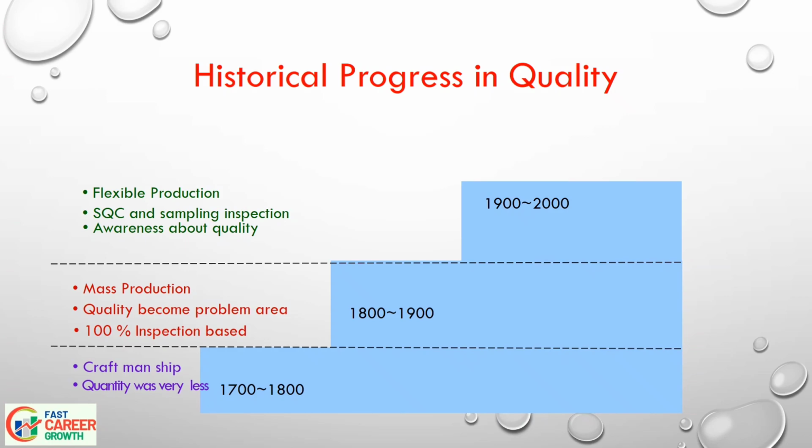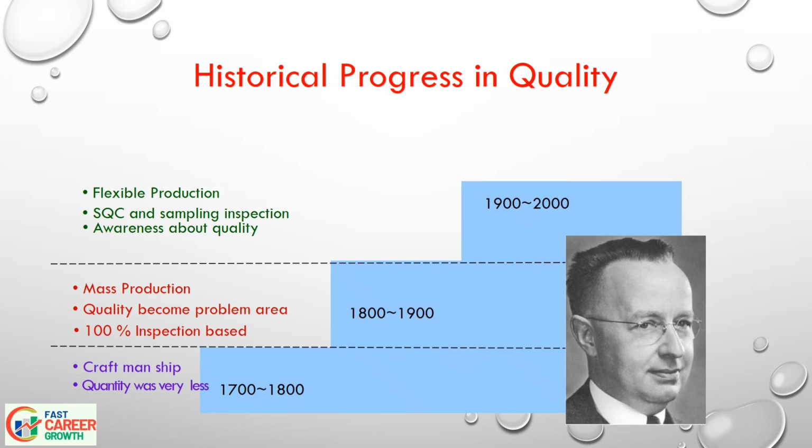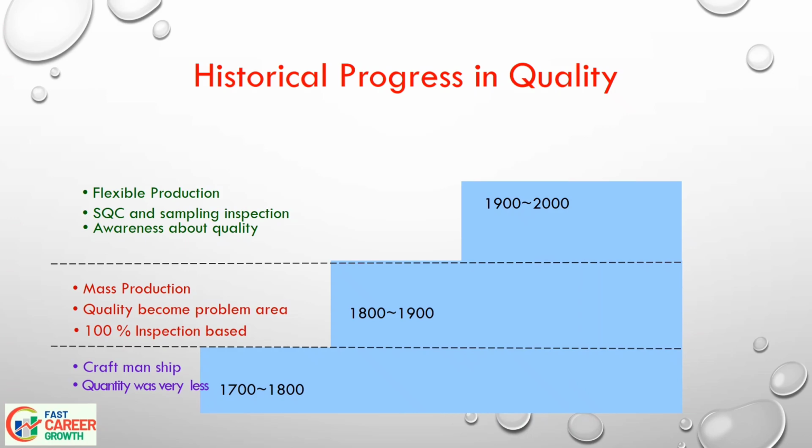In 1924 Walter Shewhart of Bell Telephone Laboratories introduced the concept of statistical quality control, controlling the quality of mass-produced goods. Shewhart believed that variation always exists in manufactured products, and that the variation can be studied, monitored, and controlled using statistics. In particular, Shewhart developed a statistical tool called the control chart. Such a chart is a graph that can tell a company when a process needs to be adjusted and when the process should be left alone.